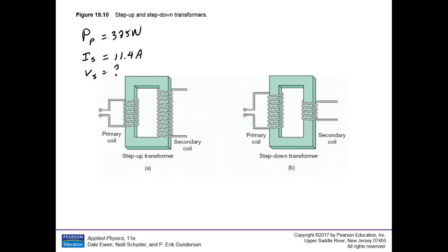They're equal. You don't create energy or destroy energy. Power is energy per unit time, same on both sides. So this is also P sub S. As soon as you know primary, you know secondary. Unless there's some loss in it, and you know there's loss.